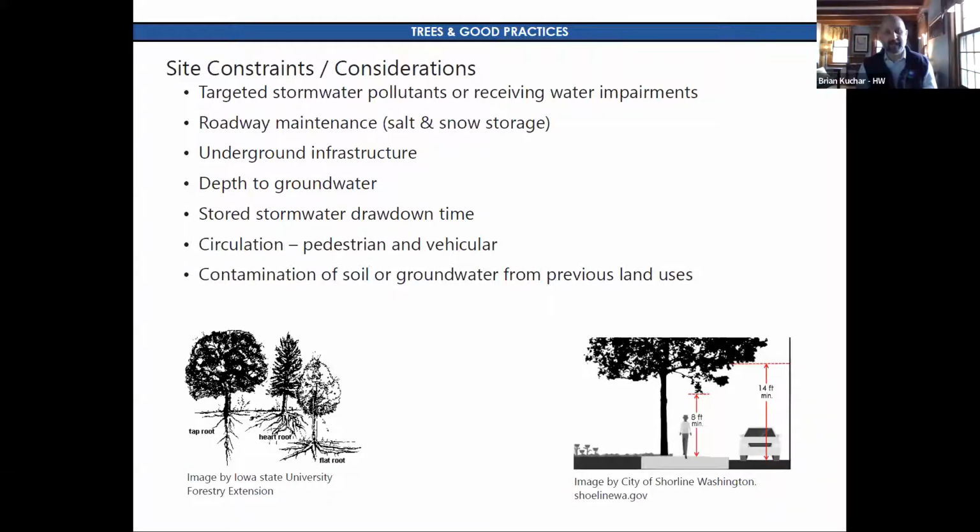Okay, well, that's good to know, because that will help us decide if we want to be surface or subsurface here. What about, we're near the pond. Should we be concerned about groundwater? We'll obviously do some test pits out there, but it's good to know before we get started if you're concerned about that. We recently dug another element in this area, and we did run into groundwater. I think the groundwater was at least 6 or 8 feet down, so I don't believe it's going to be a problem here. That's great, because those depths should work.